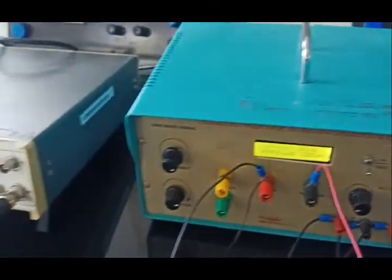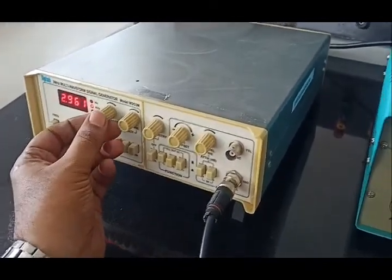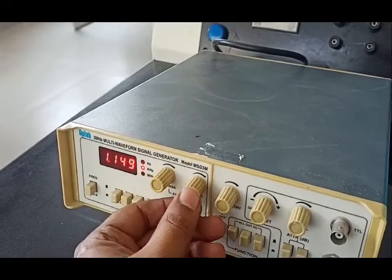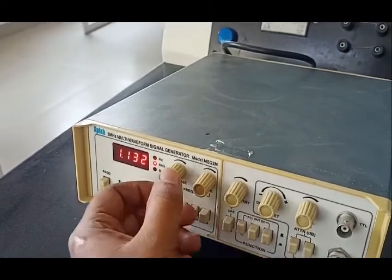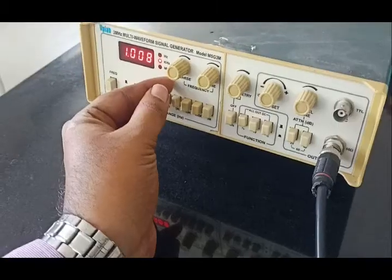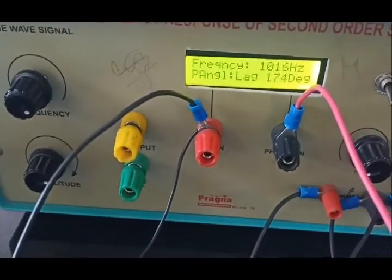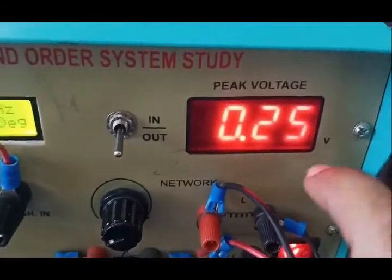So now let me directly go to 1k. So now I would set it for 1k using the signal generator, and you can observe here the phase angle is 175 degree lag, and the output voltage is 0.25.